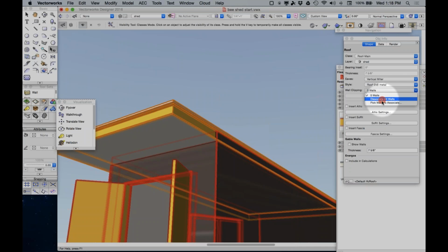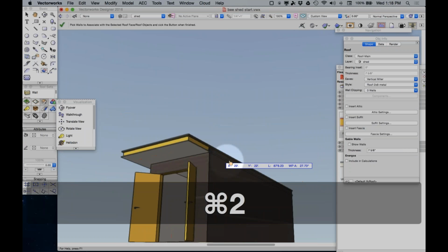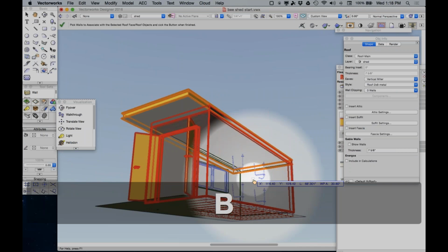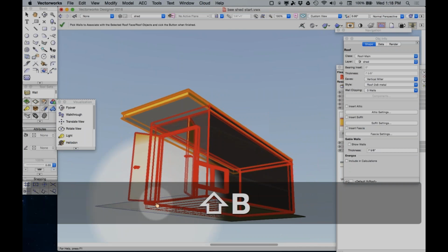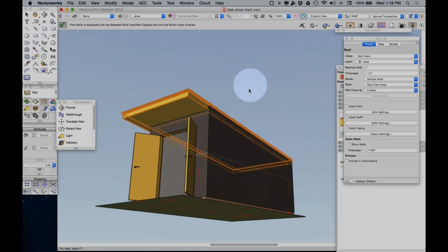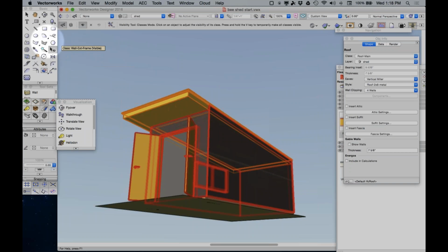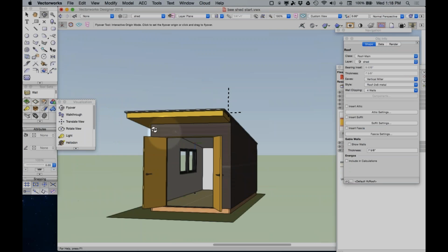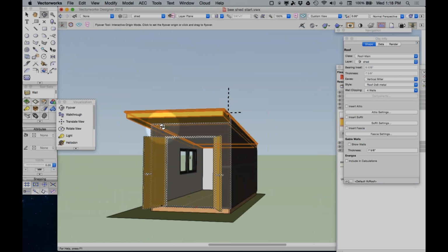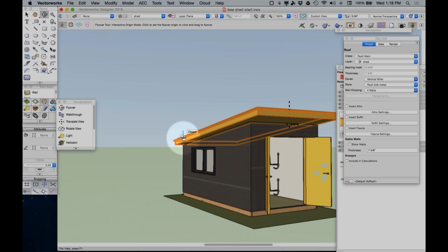All right, so if I pick some walls to associate, then I can click on this wall and that wall, maybe use my zoom loop to be able to see through the model in wireframe mode, and select all 4 walls and then hit this little checkbox, and then you can see that the roof reshapes in order to reflect the association that it's got. So I've got walls and roofs that are interacting together in Vectorworks really nicely in order to give me the model that I want without having to do a lot of custom modeling.